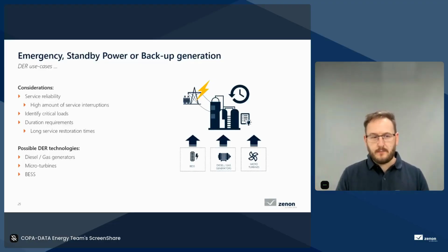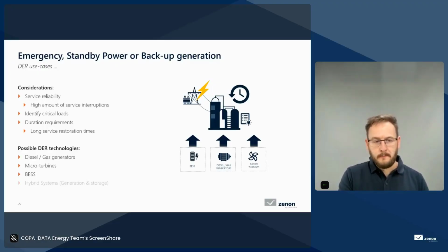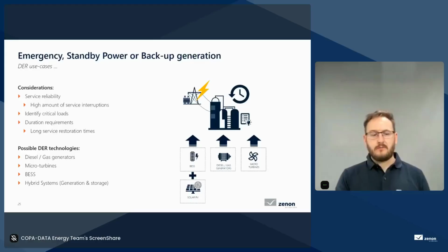Zinc bromide batteries have more of a medium duration, but are slower to respond. This is what we need to consider when we look at battery technologies. And of course, we can make our emergency standby backup power generation even more flexible if we combine our storage with a hybrid system, for example, generation and storage.